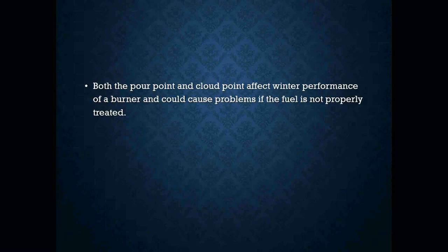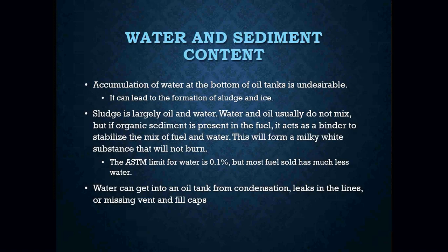Okay, so sometimes if you put in the wrong additive, you can actually almost destroy or break down the oil, and then you're going to have even more issues. You have to obviously make sure that you're following the recommended treatment rates. You have to make sure that you're following all of your safety and handling instructions on the label and any safety data sheets that should accompany that sort of additive. So it's not just simply taking something and throwing it in an oil tank and calling it a day. You've got to make sure that you're doing it correctly.